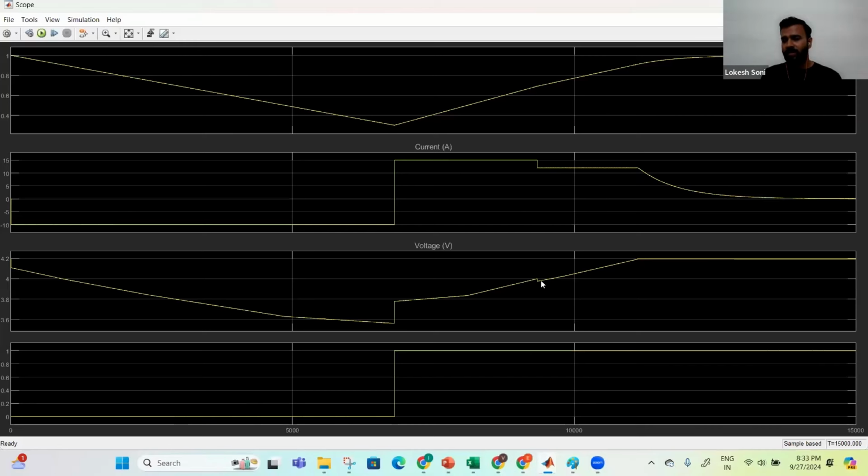Once my reference logic is met for MCC, the second CC phase is starting. If you want more CC, you can do that. Here still CV is happening, right? As I told, if you want to completely eliminate the voltage control circuitry in your charger, you can just have multiple CCs. Okay, let me just take a new snapshot.